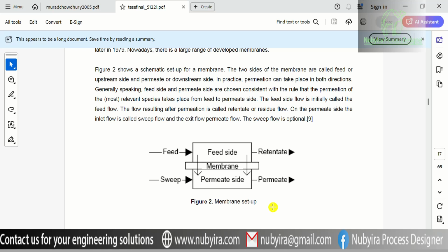The flowsheet for most of the system is a continuous flow system where you have a membrane separation pressure unit. Then you have the feed that flows through one side of the membrane. The flow can be countercurrent or co-current. Then you have a strip gas to strip off the permeate, or the gas diffused through the membrane. The remaining gas is taken as retentate, and you can have multiple stages connected together in order to increase the efficiency of the whole process.